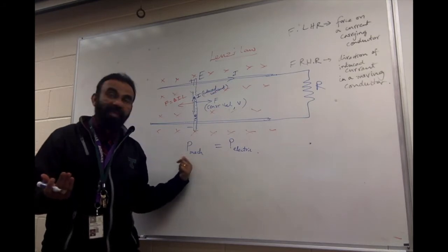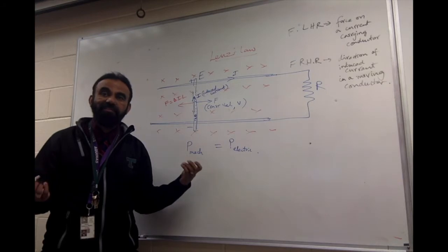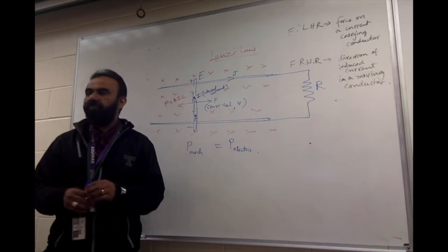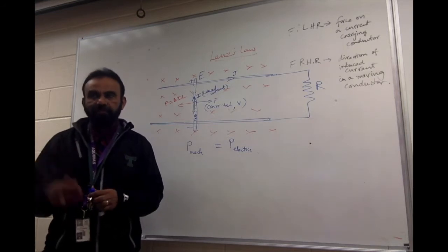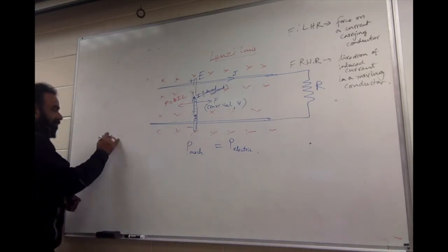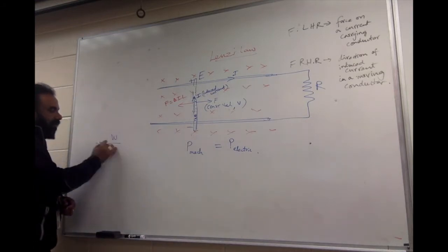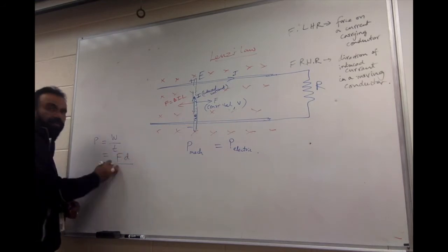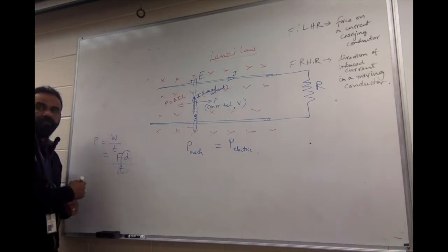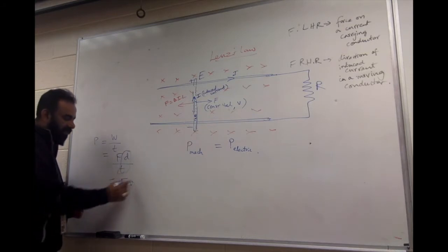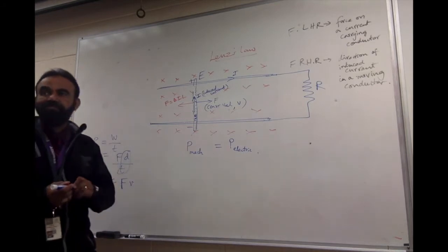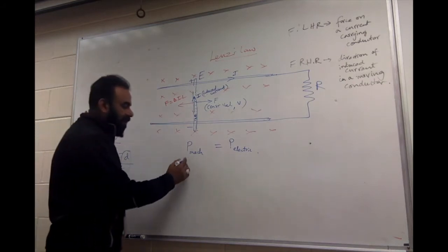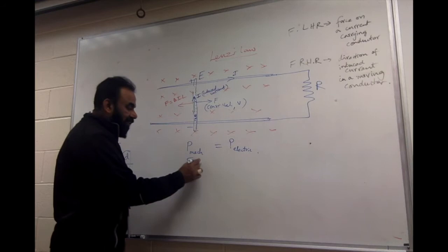What's the formula for mechanical power? You've done it last year. Mechanical power. What's power? Work over time. So what is that? All right, here we go. Work over time is power. And work is force times displacement. What is displacement over time? So it's F times velocity. You did it last year, forgotten already? So mechanical power is F, the force that you applied, times the velocity.